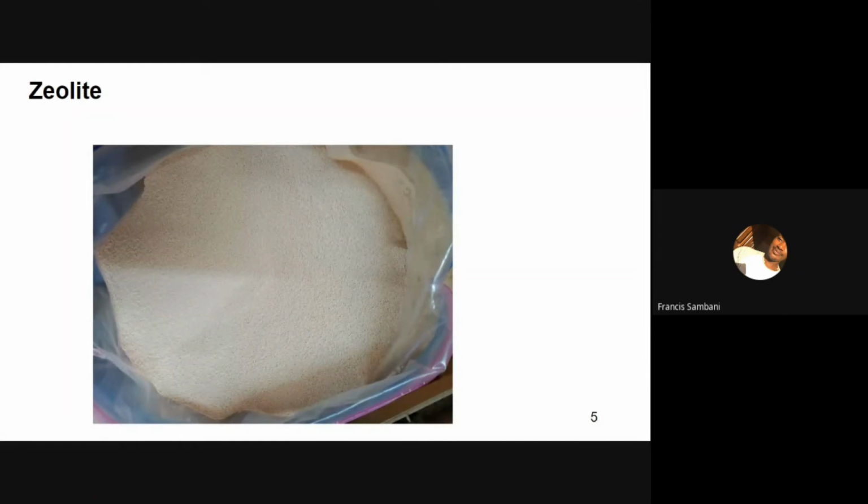So the pressure swing adsorption, also known as the PSA process, is a static separation of air gases via a specific molecular sieve designed to absorb nitrogen under high pressure. So air is composed of 78% nitrogen, 21% oxygen, and 1% other gases that can include argon, and other gases.